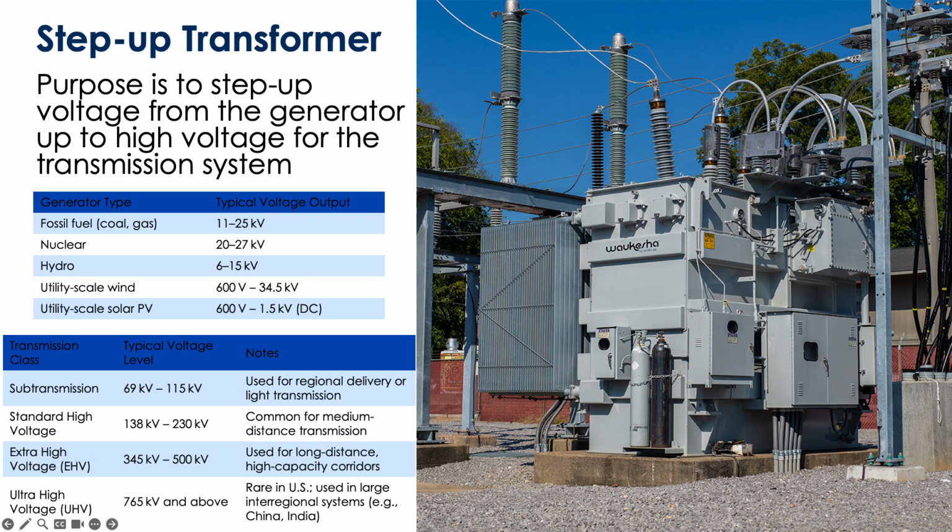So these are often producing power at voltages that are more in your distribution level. And so in fact, if you could get this stuff located right at the location where you're consuming the power, you're already at your distribution voltage level. In theory, you might be able to avoid some of the losses that would be happening as a result of stepping up the voltage to some of these extreme voltages for your transmission system.